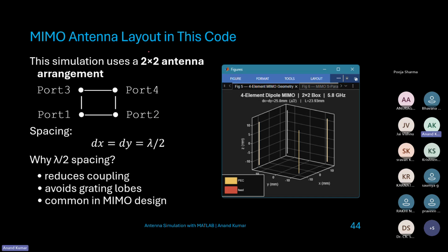So a typical MIMO antenna layout is just the different antenna elements. They might be the same element, or they might be different types of elements arranged together in some spatial way. For our case, we'll use a very simple case to demonstrate. In the examples we'll have four elements. The main example that we'll discuss is the dipole. So we have four dipoles arranged in a box way.